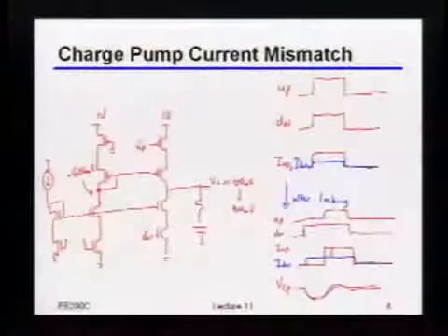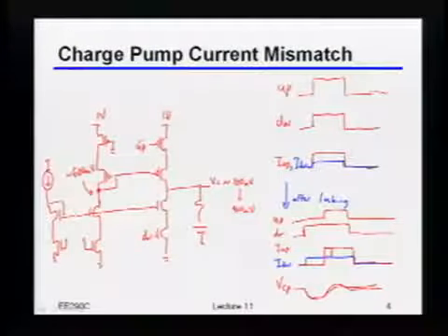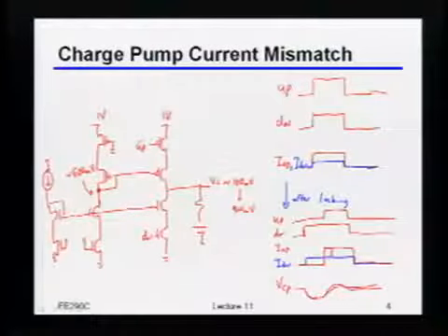The only reason I was making different pulse widths was because I was trying to correct for some jitter in the first place. Here, even if there's absolutely no noise, I will create this glitch. So especially if the current mismatch is big, I could get a really big static phase offset, and then that reference spur will be proportional to that static phase offset and could be much larger than the noise I had in the first place.